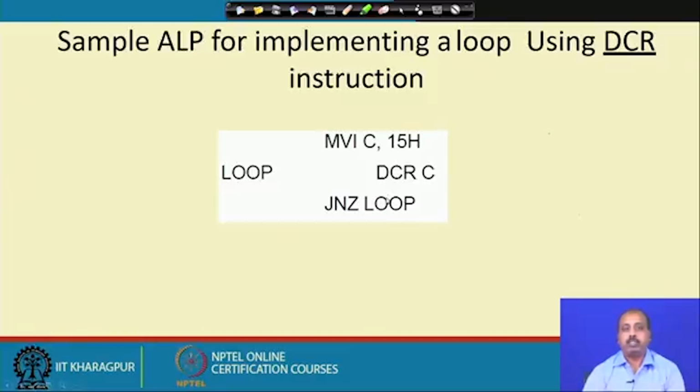For example, if you have output some pattern onto LEDs or some LED display, human eyes will not be able to follow if it is changed very fast. So you want to put some delay for the eyes to understand the display. We can put some delay by using this type of delay routine, and after that we can change to the next pattern, so that the display becomes stable.